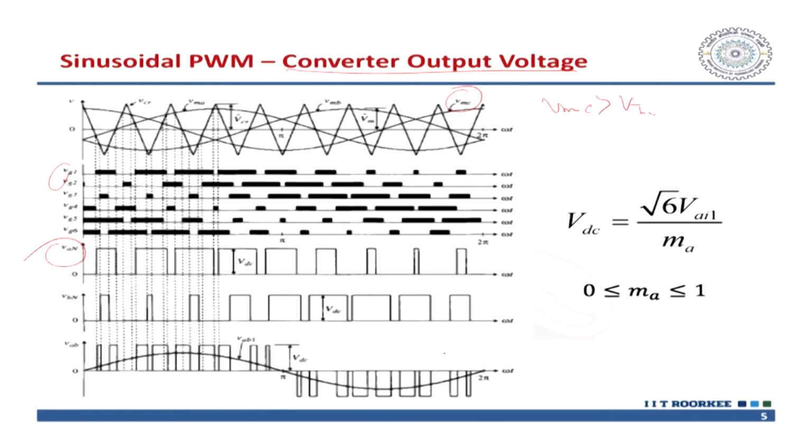Please understand that you are required to provide an inductor. Why? Because ultimately this sine wave matches with the pulse width modulated waveform on average, but there is an instantaneous variation between the PWM voltage and the voltage at this point. So, for this reason we require a buffer inductor, and thus the calculations of LF, the inverter side inductor, and the grid side inductor come into the picture.